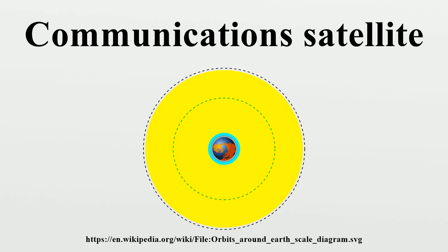Wireless communication uses electromagnetic waves to carry signals. These waves require line of sight, and are thus obstructed by the curvature of the Earth. The electromagnetic signals that communication satellites work with have a large spectrum of wavelengths and frequencies. To keep these waves from interfering with one another, international organizations have certain rules and regulations describing which wavelength a certain company or group can use. By separating out wavelengths, communication satellites will have minimal interference and be able to communicate effectively.